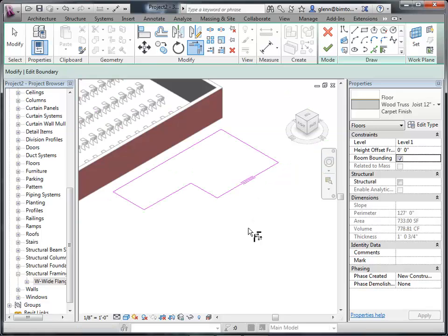So when you're drawing, it tends to be pretty easy to control this stuff. You can sort of see what you're doing. Hopefully you can clean up the boundaries. You just basically have to go through and kind of complete the boundary. Now, another variation I'll just let you know about when we're talking about the boundaries is if you want to create a hole in the floor because you want to put a big atrium in the building, or you want to put a hole for a stairway or a shaft or something like that, how you do that is you put another loop within the loop.